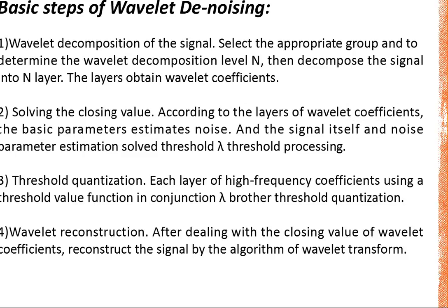So here are the basic steps of wavelet denoising. First, wavelet decomposition of the signal. Select an appropriate wavelet to determine the wavelet decomposition level and then decompose the signal into n layers. Each layer obtains the wavelet coefficients.